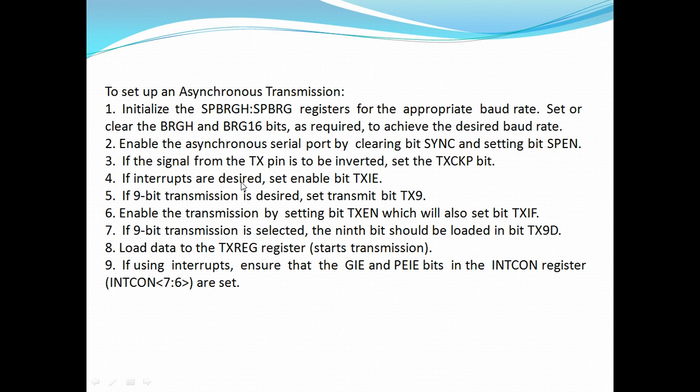In the third step, we have to set this particular transmission pin. If it is inverted, then the TXCKP bit should be set to 1.